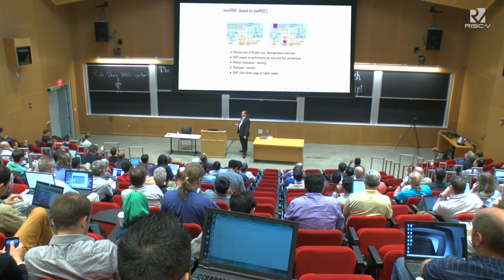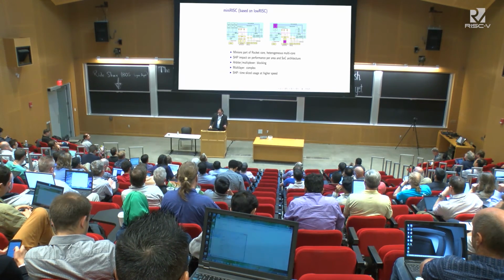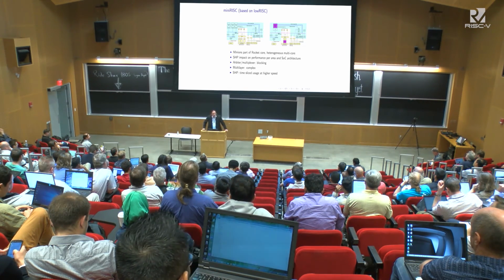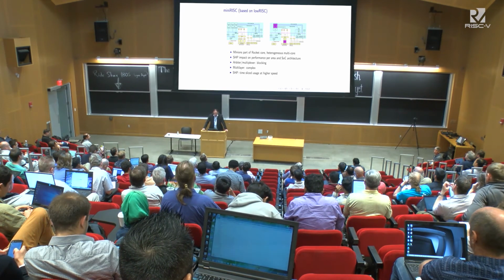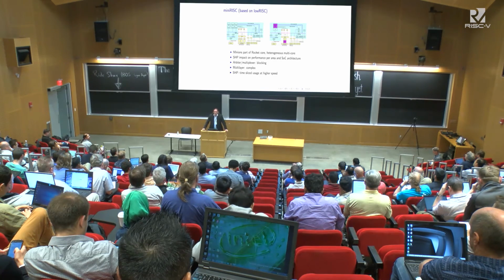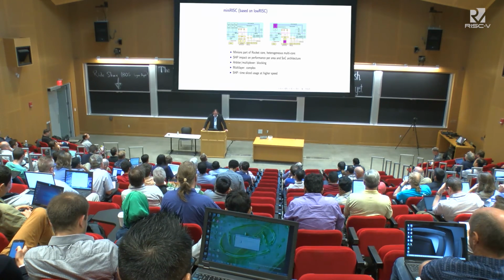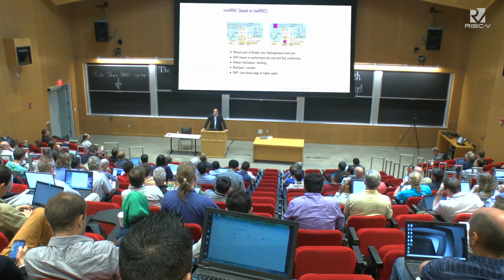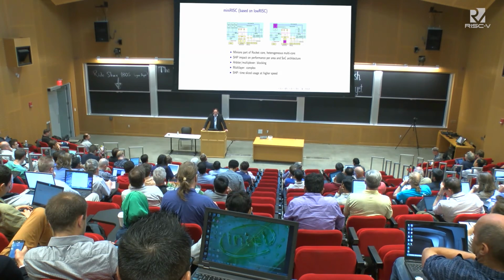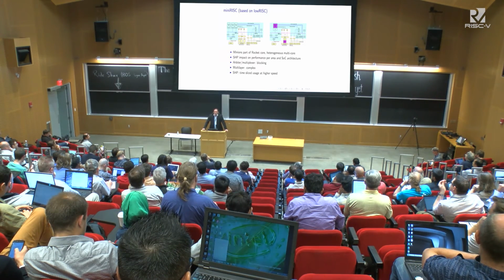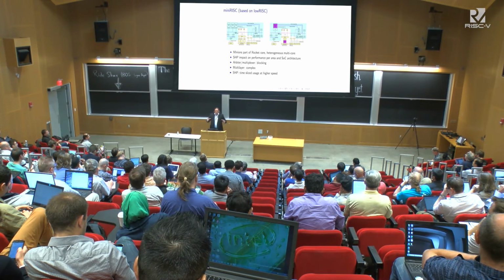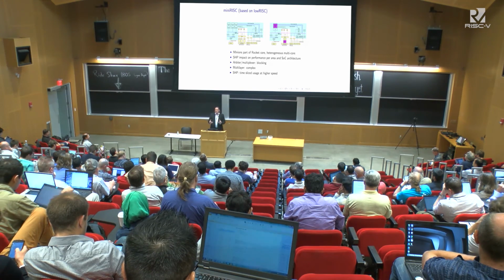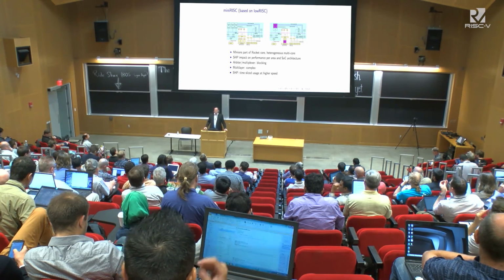And the next system level aspect is that instead of having a multiplexer-based system bus, which is kind of blocking, or a multi-layer bus, which is complex, system hyperpipelining has an impact on the system bus because I can use the system bus quite naturally in a time-sliced fashion, so it's less blocking. So it will be a one-to-one replacement of the original one, so the same software can run, but it will be smaller, it will be faster, and have a higher system throughput. That's the whole idea, and you can then add additional improvements.